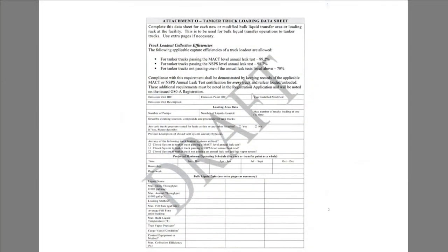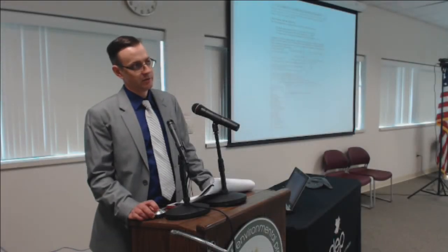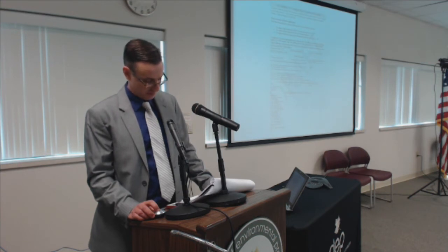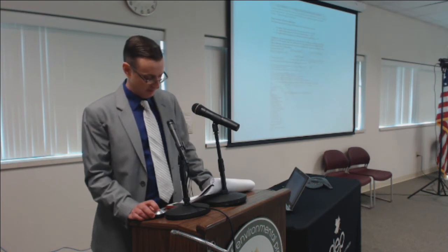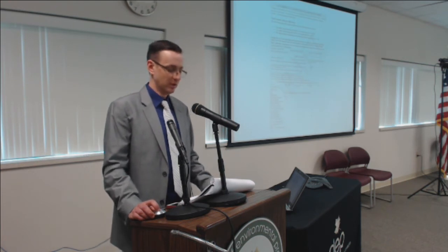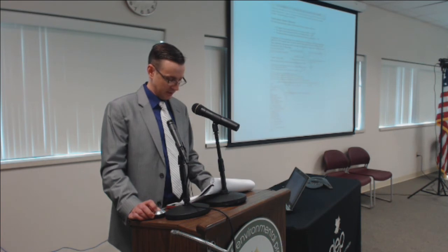And it'll ask for the types of liquids that are loaded, the number of pumps that you have, how many trucks are you going to be having loaded at one time. Talk about cleaning location. Are they pressure tested? Your operating schedule of your loadout. And what kind of liquids are you going to be loading there? Is it going to be condensate and produced water, or just one or the other? What your throughput is on a daily basis, what your throughput is on an annual basis, and loading method utilized.